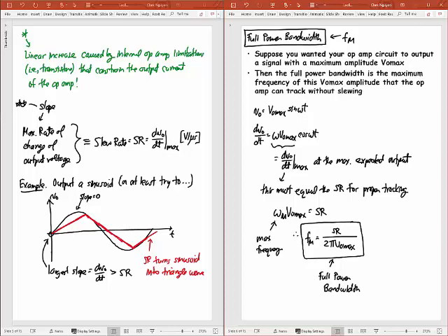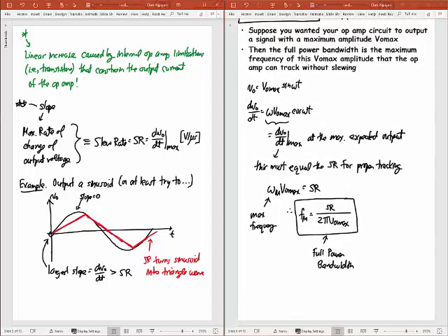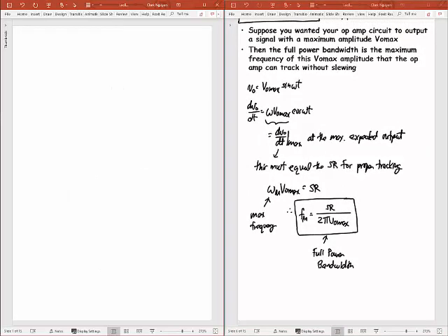So the next one I want to talk about is something I sort of touched upon in a previous lecture, mainly because I wanted you to know about it before you went to your lab, and that's the input offset voltage. And so those of you who had your lab today maybe experienced this right away. And basically, if you don't know about it, it's going to debilitate your op-amp completely if you have it open loop. Okay, so let's talk about this.